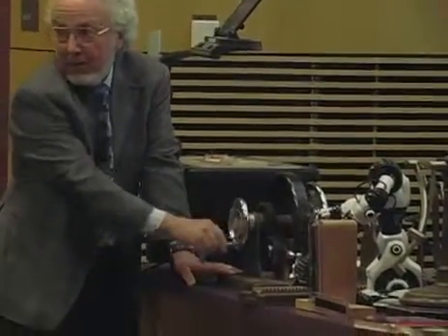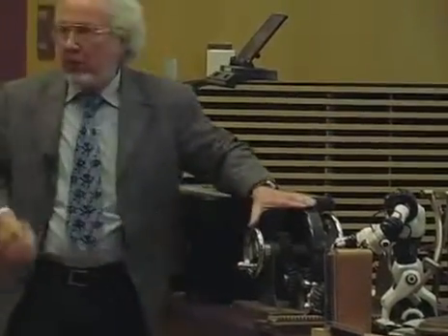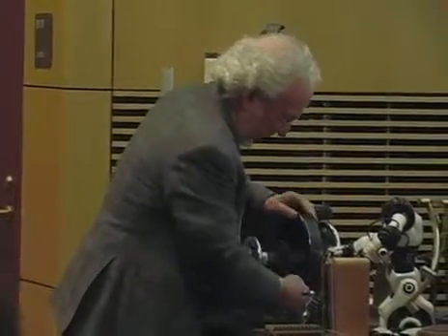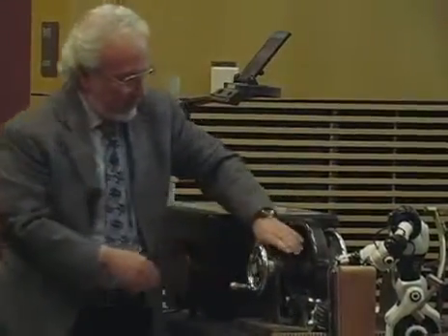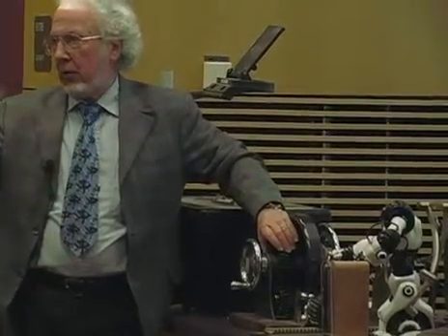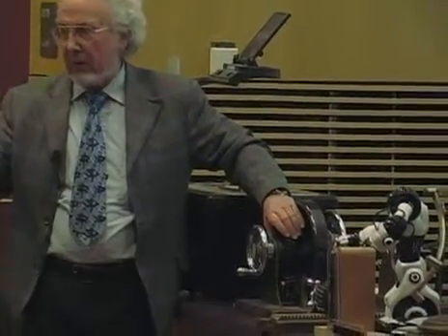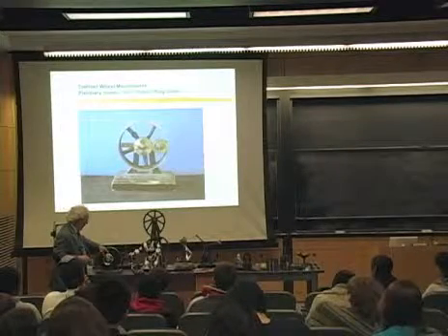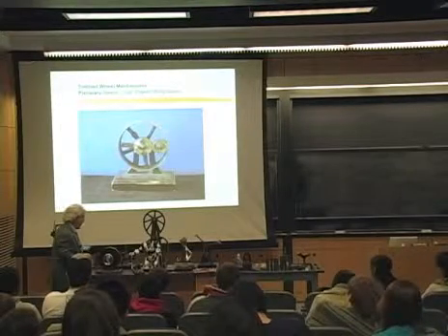Okay, and so these are sometimes called differential gears. They can either be one-input devices, or if I unlock both of them, they can be 2-input devices. And these are sometimes used in mechanisms to design a wrist mechanism in robotics, but they may be in the shape of more bevel gears.